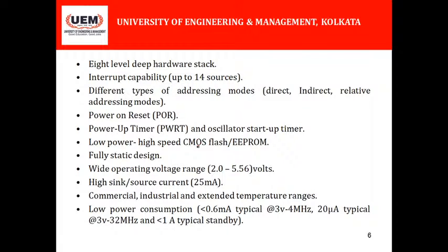Different types of addressing modes are supported in this microcontroller, such as direct addressing mode. Direct addressing mode may be of two types: memory direct and register direct. Whenever we are retrieving data from a register directly, it is register direct. When we are retrieving an operand from a memory address, it is memory direct. Indirect addressing mode is of two types.